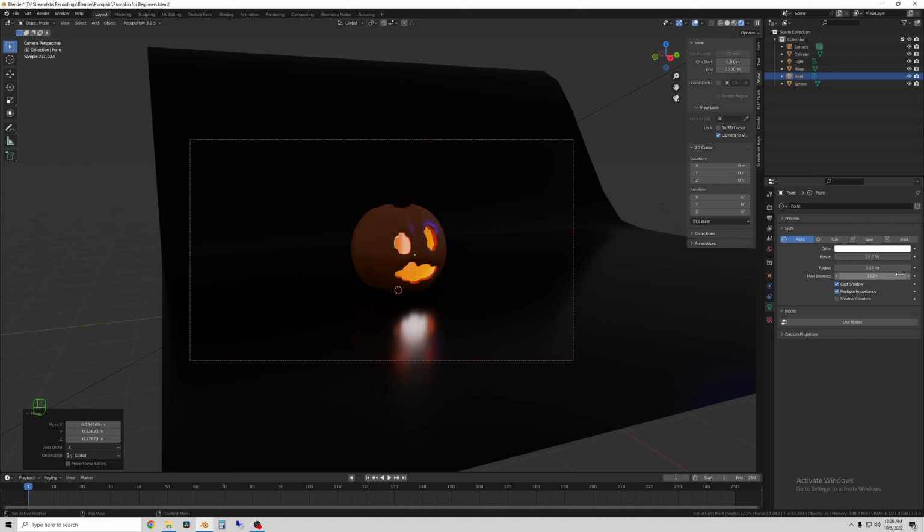One other important setting with these, though, is to change the radius. You should think of that as basically how big the light is for a point light. So if I make this really small, you can see it looks like a little candle flame. And then if I play with the brightness, you can tell it really cranks it up. If I bring it down, it's almost nothing. So I'm going to leave mine at the 20 watts, but make it a pretty small radius. Mine's 0.04. I think that looks okay.